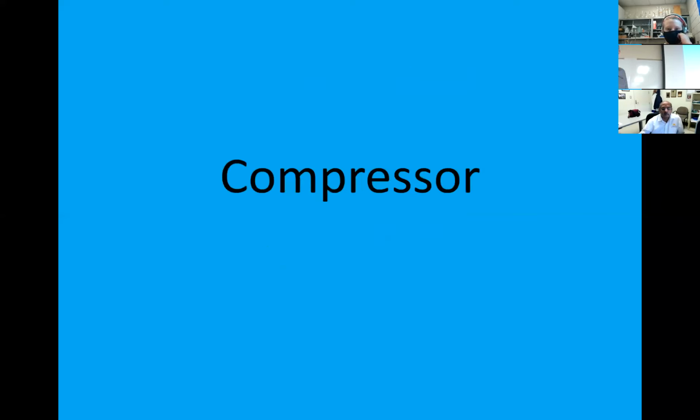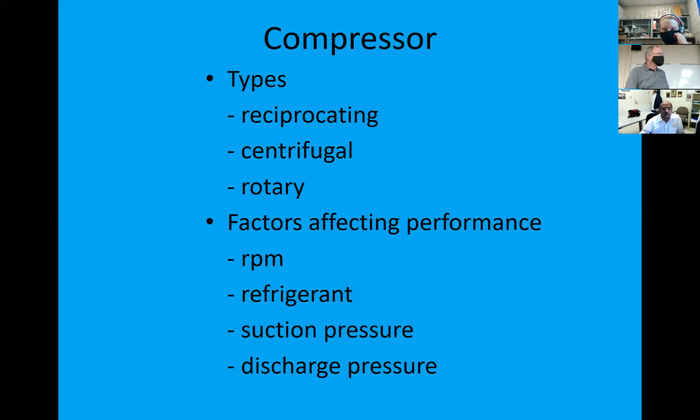The compressor, what are we going to do here? We're going to take that vapor and start to bring it back around to a liquid for us. There are a lot of different compressor types. Basically, what type of pump are you using? Reciprocating, centrifugal, rotary, anything that will take that vapor and squeeze it back down to a high pressure vapor, which we then will later remove the heat from.